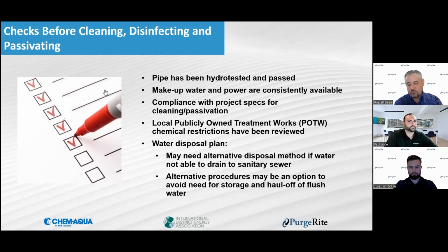One is we are considered a third-party flushing company, so we're bringing in external equipment, as you saw in some of those previous slides, external pumps and filtration, et cetera. And we hook that up to not use the house pumps or the systems that are in place for the client, and to reach the velocities and to clean these systems. And before we show up, the piping needs to be hydrostatically tested and passed.